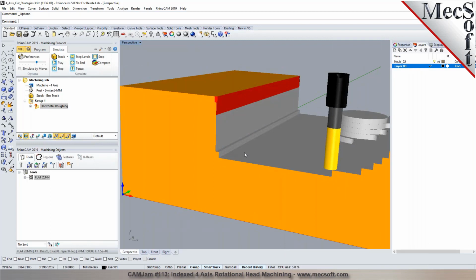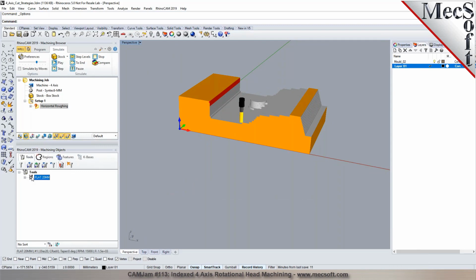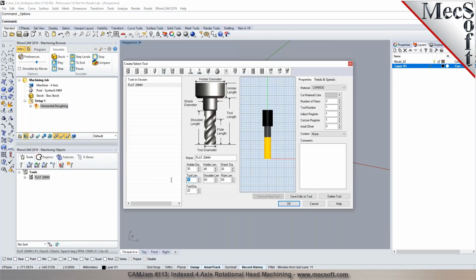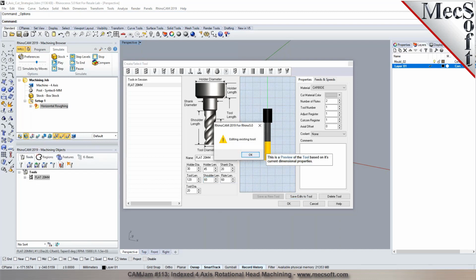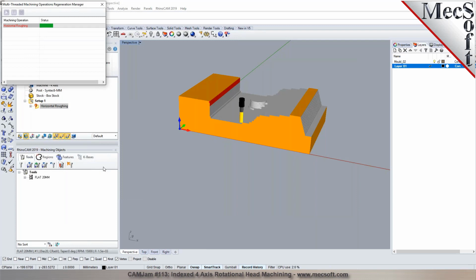Since we're cutting down 100 millimeters, you can see a collision right there. We're probably going to be better to lengthen the tool, to have a longer tool. So we wanted to go maybe 120. Change that. We'll save it as a tool. We'll regenerate the path. Do you have any questions so far? No, I'm following all that.